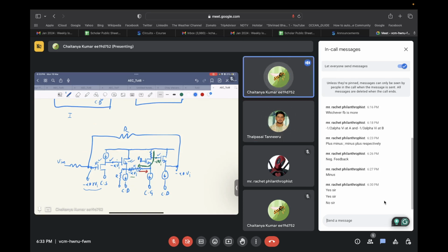Whenever you are designing a circuit, you should keep in mind that the square law model doesn't work. In order to set the current density, width, and length of the transistors, you have to use MOSFET characterization using the GM by ID method. You do the first iteration, run the circuit, and you have to do two or three iterations to get to the final product.